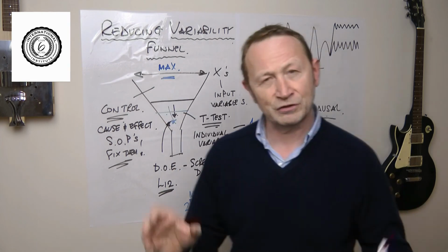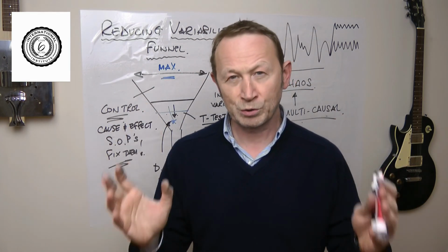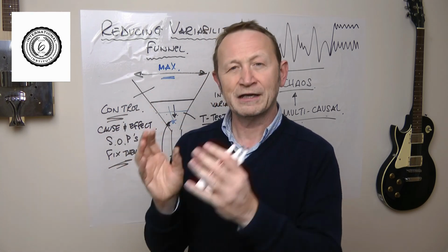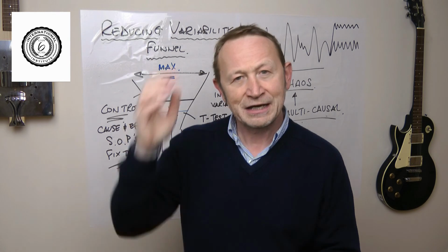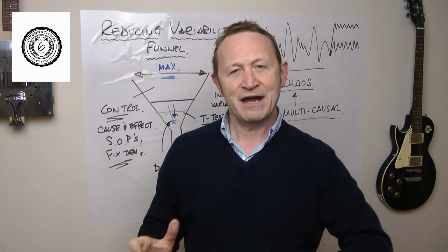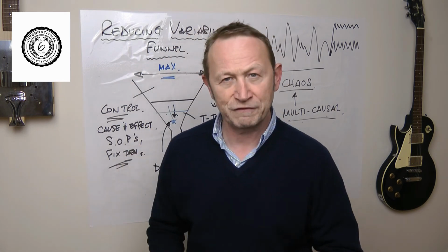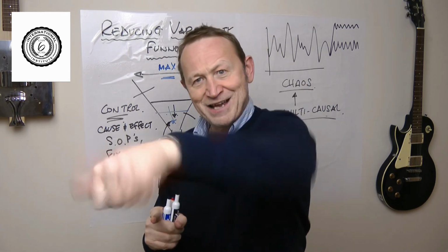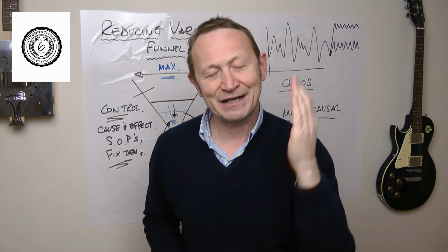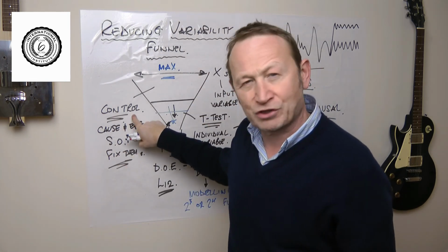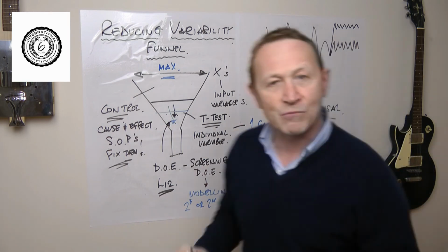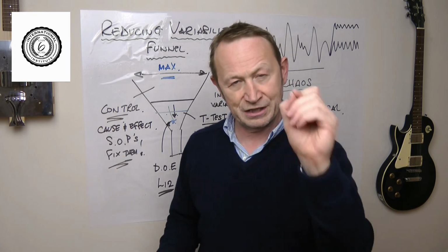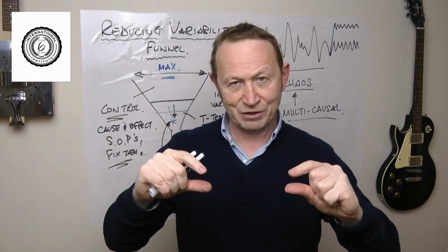Initially, the top of the funnel is just control. Always remember this. If a variable is not allowed to move, it cannot be your enemy. It cannot be the problem. And if a variable doesn't move, don't allow engineers and technicians to walk up to it and swing on the dials. That is unacceptable. That is not control. That's beginning to allow more chaos to come into the process. So get the process under control, adhere to rules, get the chaos out of the process.